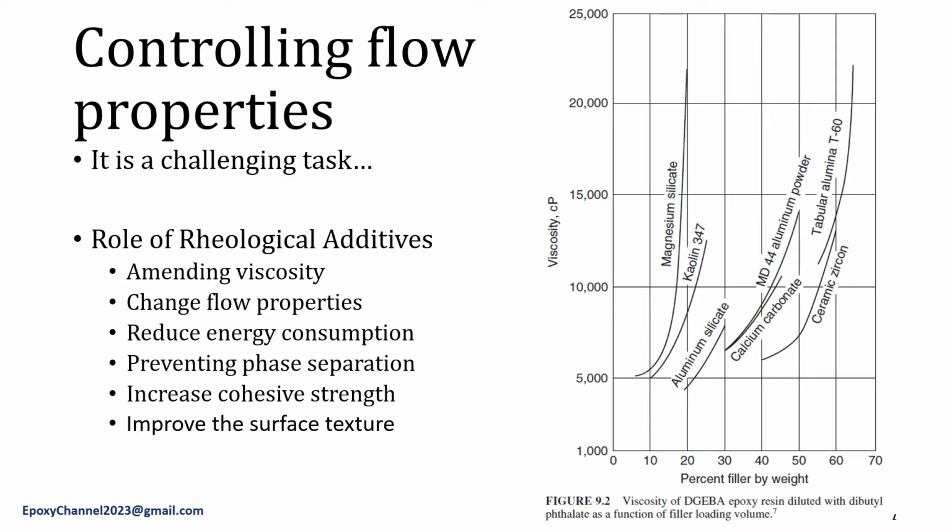Fibrous fillers cause a larger viscosity increase than do particulate fillers. Finer filler particle sizes having a large surface area will greatly, but not always, result in higher viscosity than an equal concentration of larger particle sizes. Increased viscosity might be desirable for adhesives. However, too high viscosity can yield undesirable processing properties. Therefore, maximum filler loading is often set by the optimum viscosity.